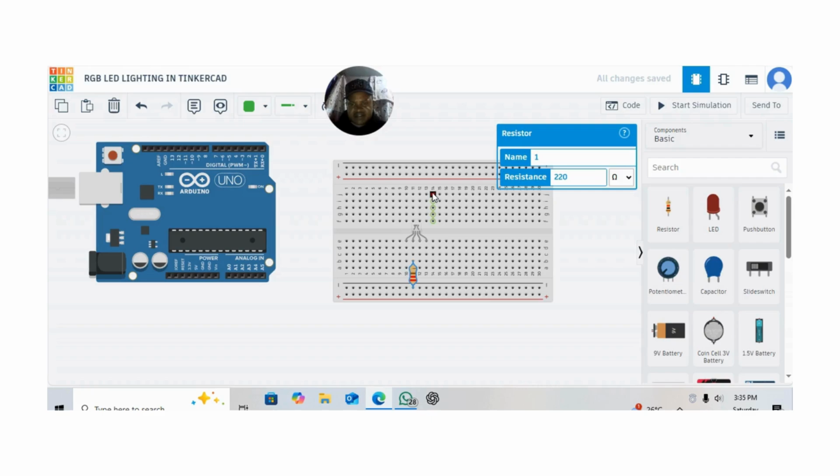connected vertically. So if I place my cursor here, I can see a green highlight, meaning that those holes are connected. In other words, it's just one conductor, and all of them have electrical connectivity in a vertical manner, unlike these two, this section and the one at the bottom, where we have the electrical connectivity being in a horizontal manner. All these also are connected, and the same thing applies to this one and the other two at the bottom.